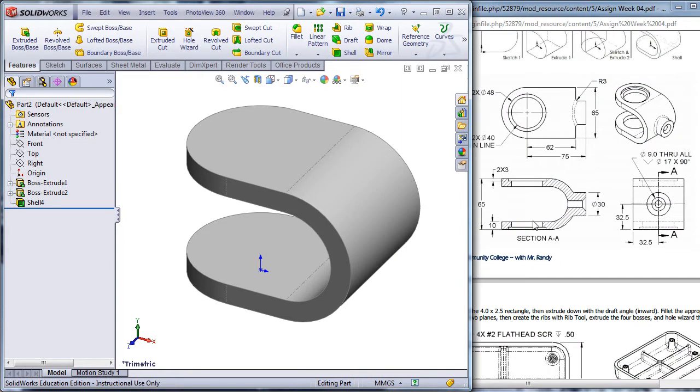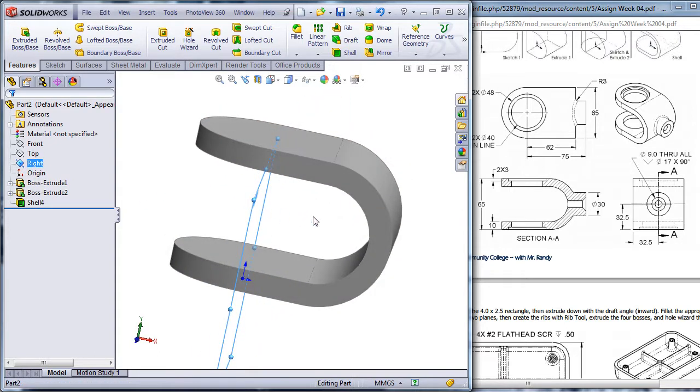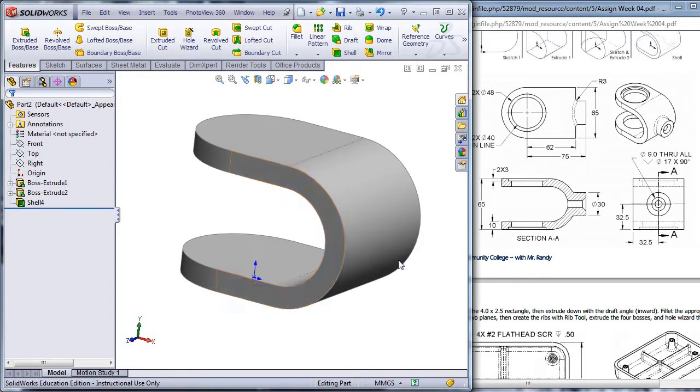When you see this part here, this nose is out here. It's at 75 millimeters. And this would be rather tough to create. You know, I could sketch on the right side plane here. I could draw a circle here and extrude it out, that 75 millimeters, but then I have this big cylinder in here and I'd have to cut it away or something. That's not a very elegant way to do this part, nor do I want you to do it that way. So what we'd really like is to have a plane out here that we could draw a circle on and just extrude it up to this surface. Okay? So that's what we're going to do.